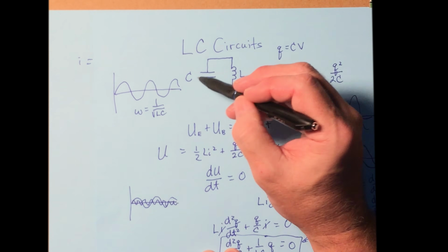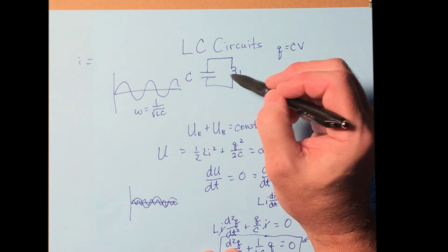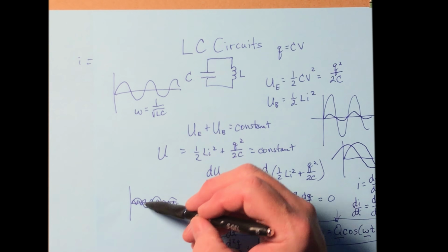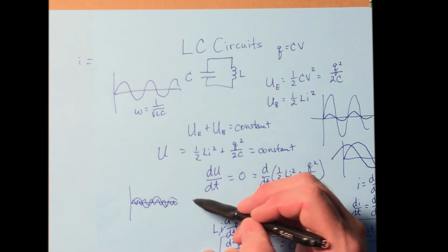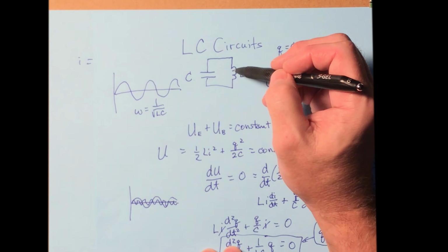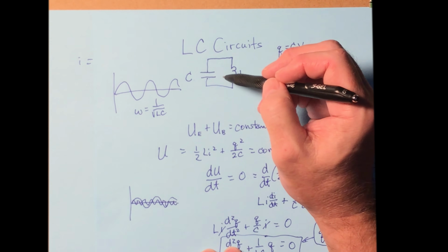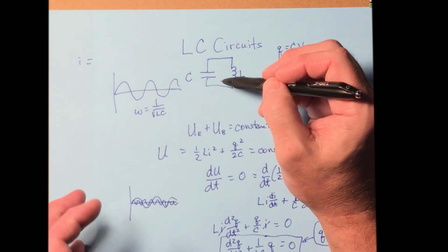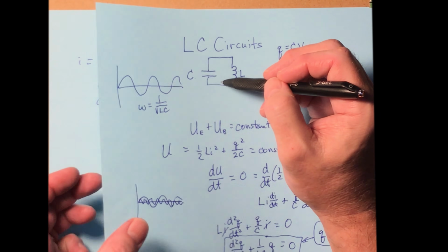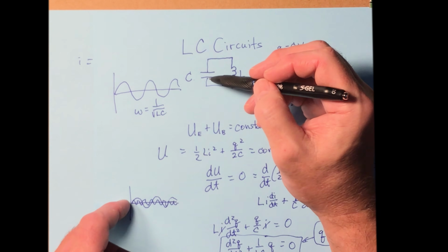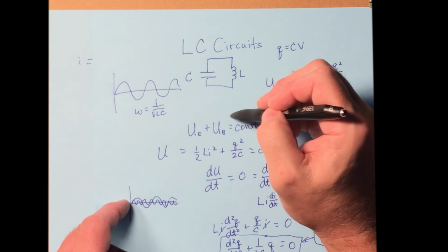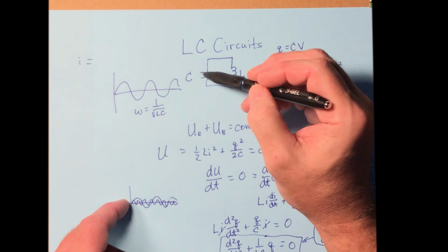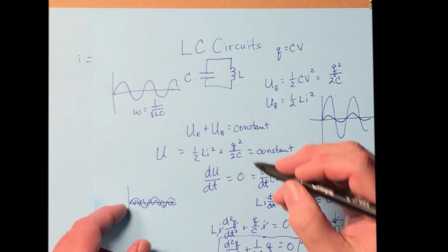So when you build this circuit, it's the L and the C values that you choose that determine how quickly it varies, either slowly or fast. All right. So those LC values then are the thing that cause the oscillation. Remember, RL and RC circuits, there was no oscillation. It was straight decay or rise and level off. Here with LC together, we have an oscillation.